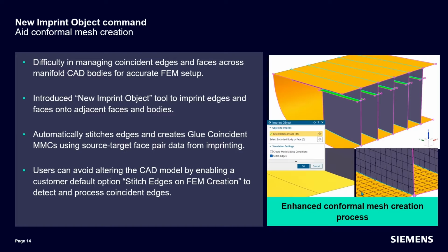Now, why is this important? It's because the users can avoid altering the CAD model by enabling a customer default option, which you might have used before, called stitch edges on FEM creation. So let's take a look at this command in action.